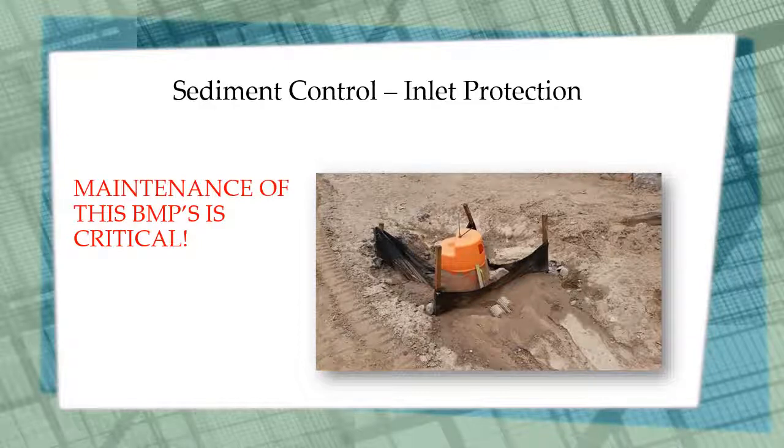Inlet protection devices must be maintained either by cleaning them regularly or replacing them regularly. You'll want to make sure that you always check the inlet protection devices during your inspections to make sure they're being maintained.